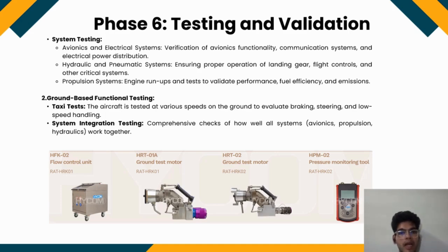After that comes ground-based functional testing. During these tests, the aircraft is tested at various speeds on the ground to evaluate braking, steering, and low-speed handling. This step is crucial for ensuring that the aircraft can maneuver safely on the ground, particularly during takeoff and landing.